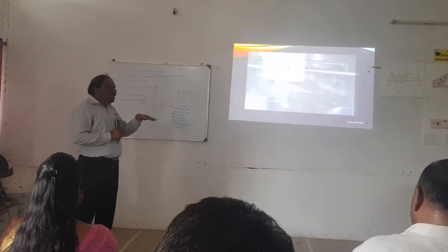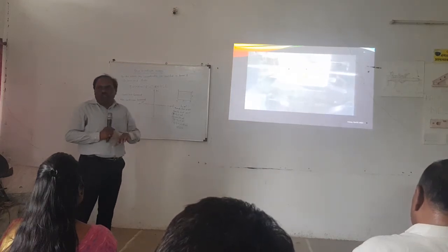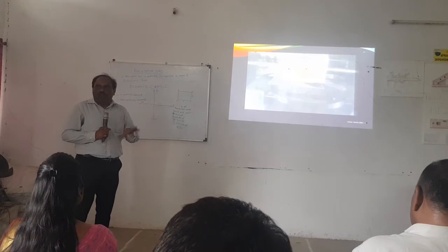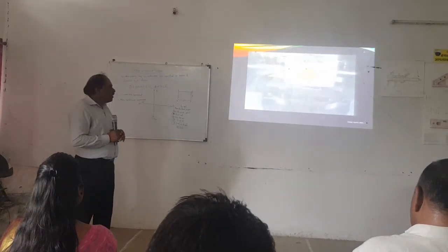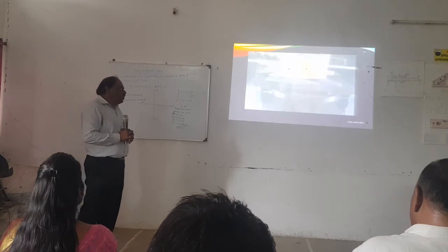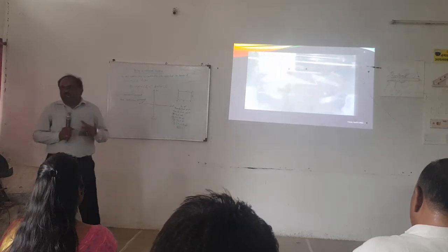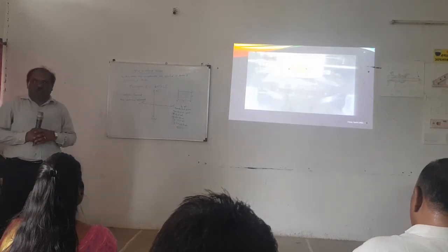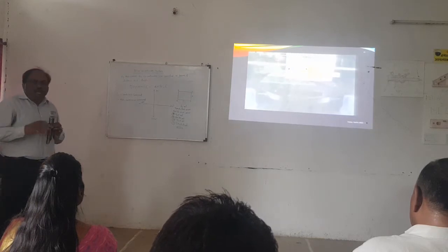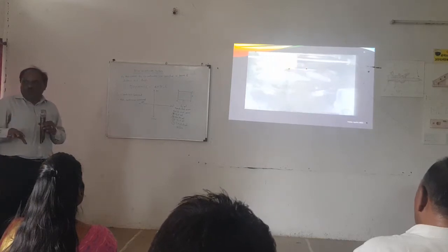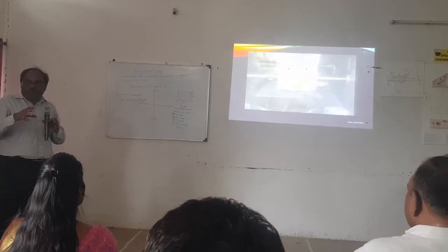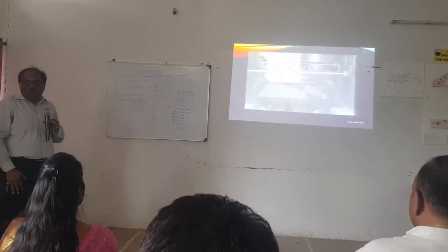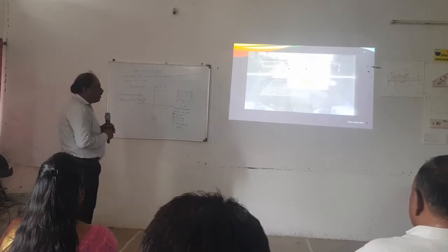It deposits the support layer. First of all it will lay the support material, then it will start the object printing. It will take a lot of time depending upon the size and complexity of the object. Then it will take some time for cooling also, then some time for cleaning also, because we have to separate the support material from the object material. That is also required.